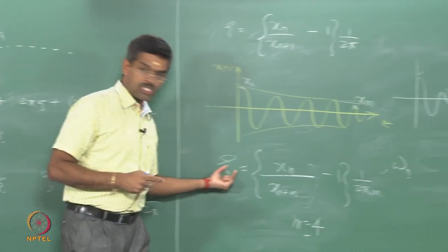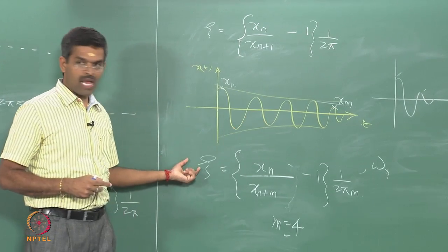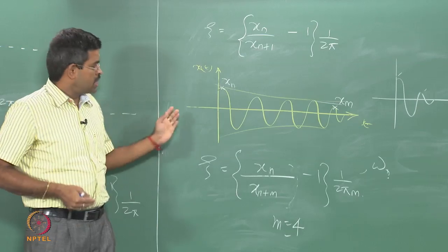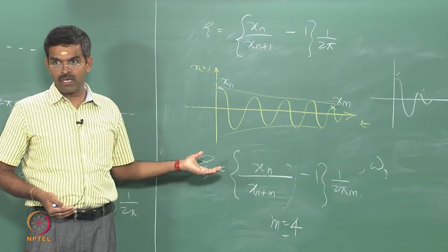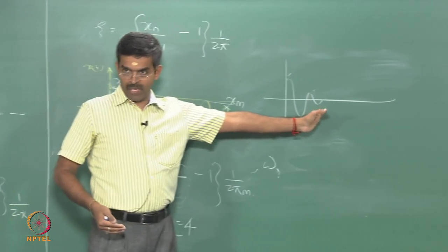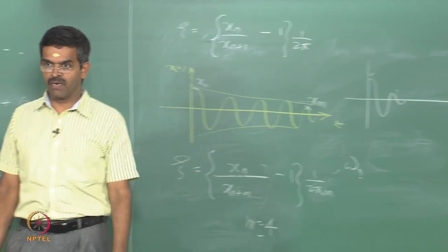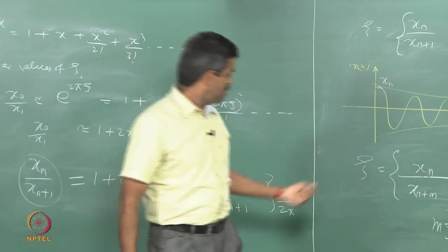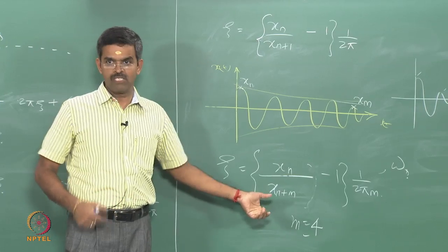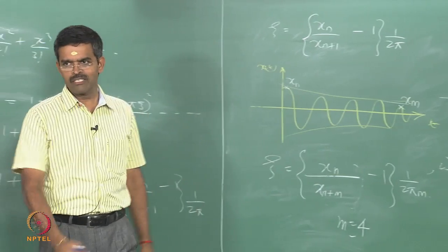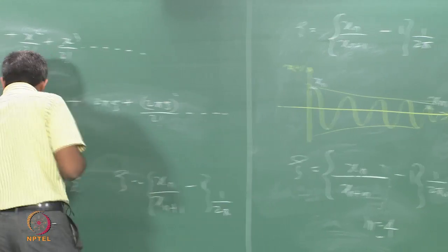Remember, it is a structural characteristic which is derived from an experiment. Therefore, this will have all errors, including the experimental boundary conditions, experimental context, scale value, material property, because concrete can be damped very quickly, whereas elastic cannot be, and so on and so forth. Be very careful about making this statement when you give a research proposal. This will include all in one. You cannot find separately from this equation. There are methods which we will not touch in this course. Okay? We will stop here for the moment, then we will move on to the next topic.